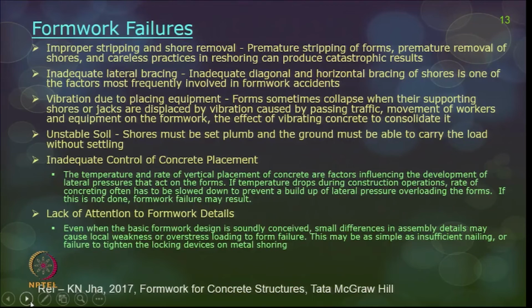Vibration due to placing equipment. So, sometimes equipment such as vibrators, okay, which move around in the site for compaction of concrete, can create vibration to the concrete and also to the formwork itself. So, the forms sometimes collapse because when you accidentally disturb the props or the support place, then the forms can accidentally collapse, and also the forms can be dislocated with the movement of workers, with the movement of vehicles moving around in the site, and also the equipment on the formwork and the actual effect of vibrating concrete.